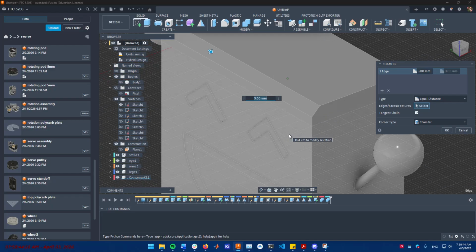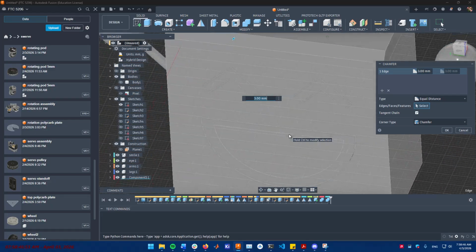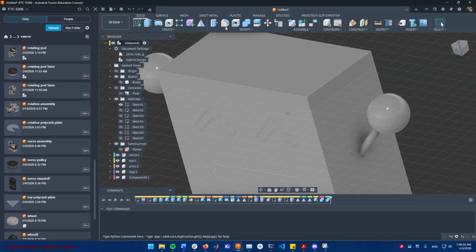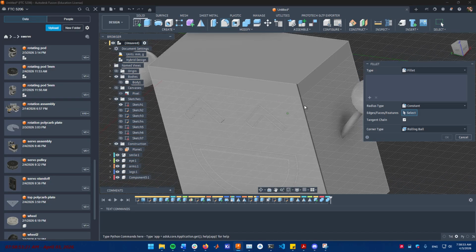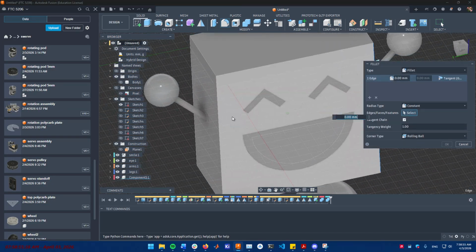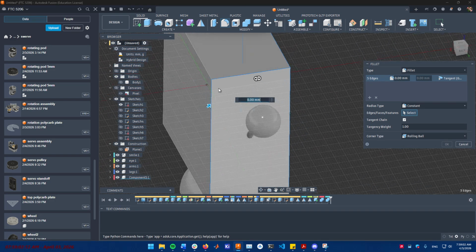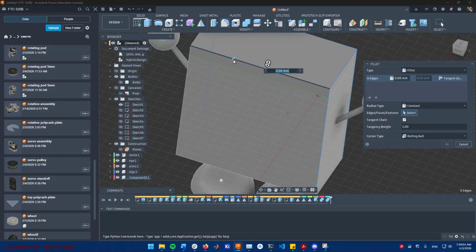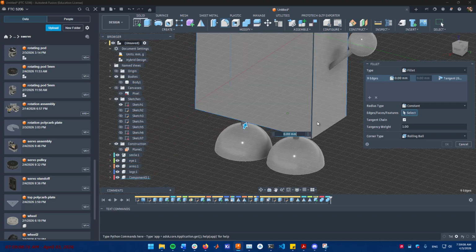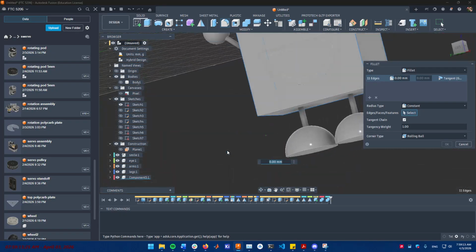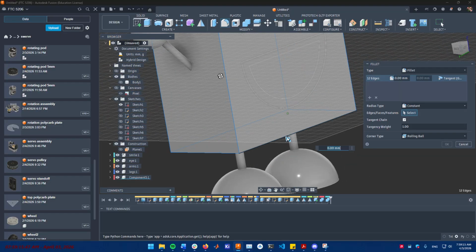doing something like this, but we can also demonstrate the chamfer by doing something like this. Right? I feel like fillet looks better on this design, but oftentimes you will find that the chamfer is also very useful, especially for top corners, because your 3D printer really wouldn't like fillets. But for now, I think it is okay. I printed mine with fillets, but they don't look that good just because the layer lines don't really align. But that is an exercise for another time.